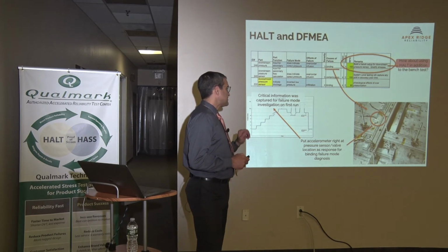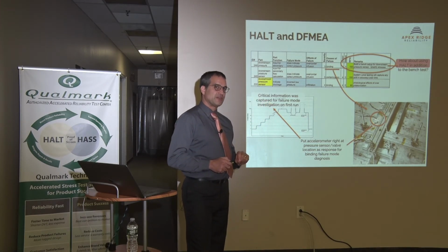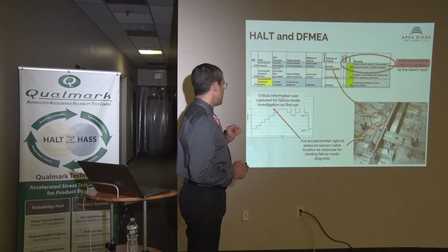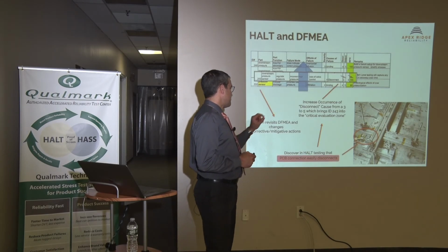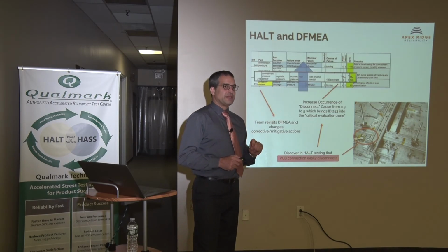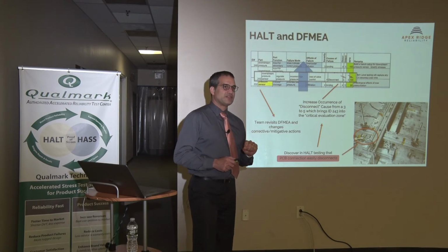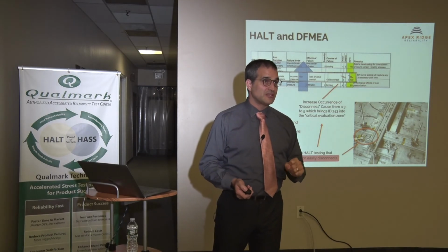So one solution is to create those large margins. So we do a HALT test. Now we know a specific area of interest, and we put accelerometers in that area for vibration to see how the sensor begins to fail and the assembly around it. And what we discover is that not only did we get good information about the sensor, but we found a nice surprise. We also found out that there's a PCB board connection that can easily disconnect. We didn't even know we were looking for that.